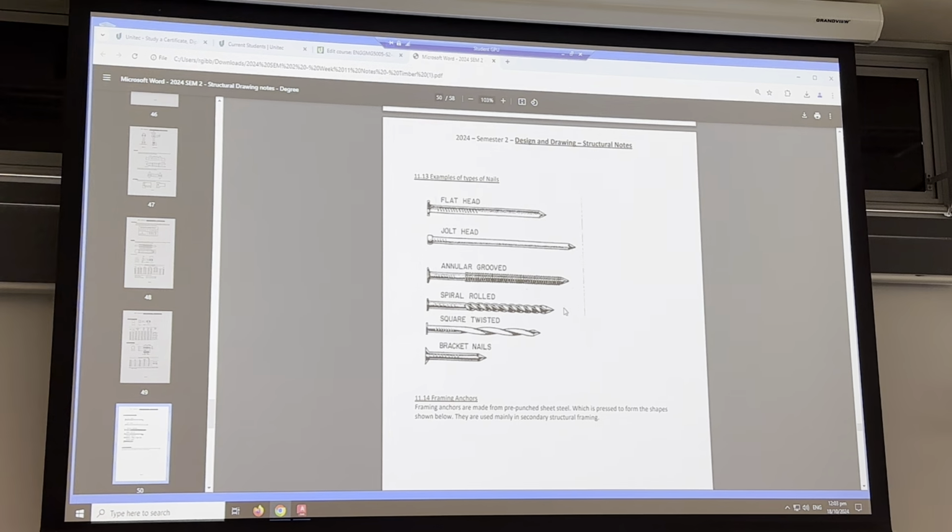So they use it a lot in packaging, but in engineering we use it a lot for, remember that sketch I did of the concrete with the false work? Yeah, so if they use these nails with the nail guns, the labourer, kind of like an apprentice, will come along and very easily remove it, ready to pull off the shuttering for a big retaining wall or something and move it on to the next job.